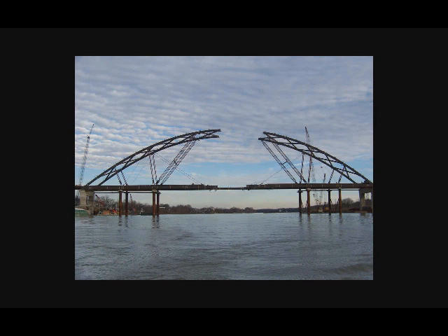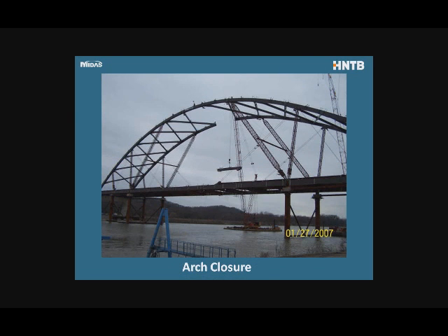So there was a planned 6-inch gap. And they had a longitudinal jacking system. There were sliding pads underneath the supports where the arch is sitting on the caissons. And so to close the tie girder, they pushed the arch together until the last tie girder element would fit.